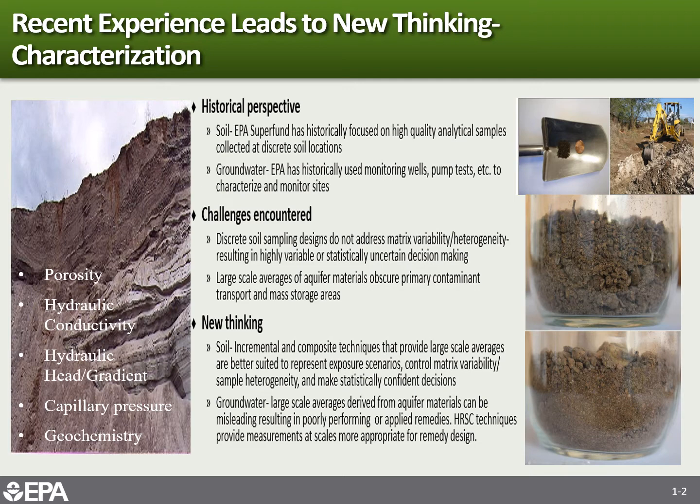Similarly, in groundwater, we've had the opposite problem where we've historically used long screen monitoring wells and large aquifer pump tests to characterize and monitor our sites. The subsurface typically looks like this example on the left, which is just a cut from a gravel pit, but you can see tremendous changes in variability in things like grain size and soil type, both horizontally and vertically. Those lead to tremendous changes in things like porosity, hydraulic conductivity, hydraulic head, even capillary pore pressure, and geochemistry, which lead to changes in how contaminants behave in the subsurface.